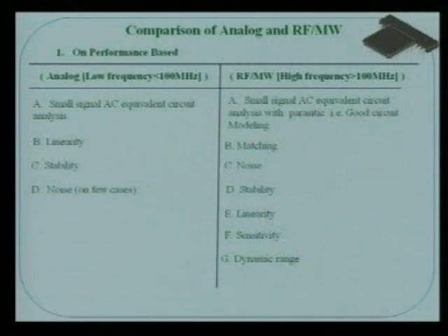Matching means you know only one matching case, that when the source resistance equals the load resistance, maximum power is transferred, right? They are in conjugate matching. But here the matching means something else. That means the S parameters, or the scattering parameters, you have to study that.